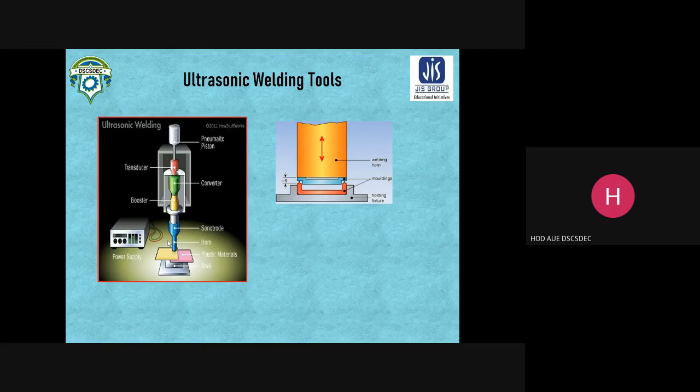If you apply stress, there will be corresponding strain, up to a certain limit which we call the elastic limit. If you remove the stress or force, the material can go back to its initial condition. Above this elastic limit, if you go on applying force, there will be permanent deformation. This permanent deformation range is called plastic deformation. Plastic deformation means the material is going closer to breakdown.